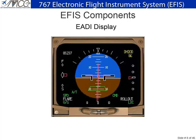The EADI displays attitude information along with navigational data and flight guidance. The navigational data consists of a fast-slow pointer, localizer and glide slope data, ground speed, and radio altimeter information. Flight director steering bars are also displayed along with flight mode annunciators, or FMAs. The FMAs display the various modes of operation of the autothrottle system and the autopilot flight director system.